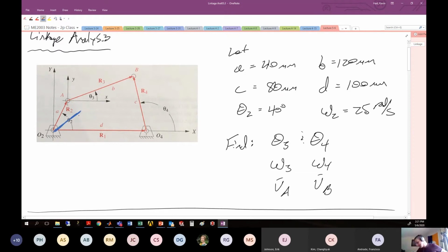And then our second link has either this angle of what we just saw for negative 61 or positive 20. If it's positive 20, it's probably going to be coming up something like this. So here is the 20-degree angle. And this is going to correspond to this open configuration where, remember, this was something like 57 degrees. So that's what your open configuration is probably going to look like.